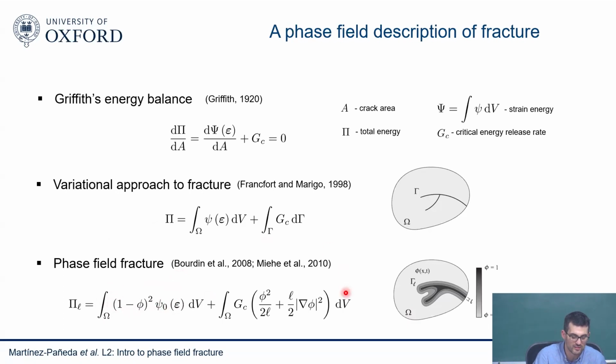The other thing is that it's a non-local continuum damage mechanics model. And that's the issue with continuum damage mechanics modeling: first of all, it doesn't link to fracture as Griffith does, but also normally the models are local, which means they are mesh dependent. Here, you get a non-local continuum damage mechanics model where you have a gradient, and because you have a gradient, due to dimensional consistency, you bring in a length scale. And this length scale plays a role in multiple ways. We'll discuss them later on.